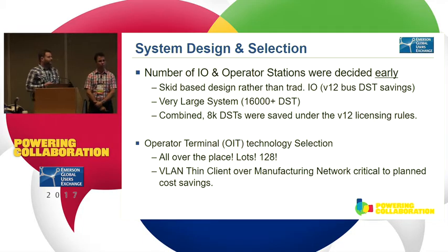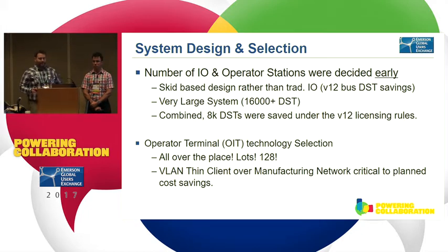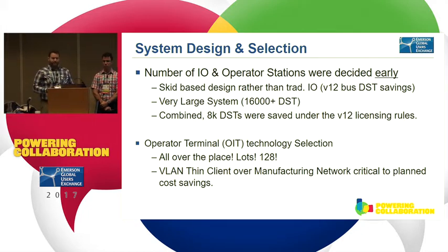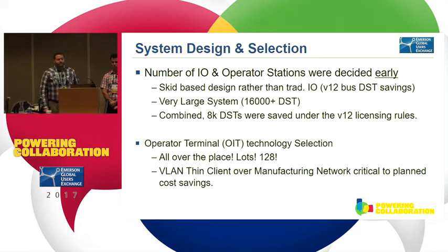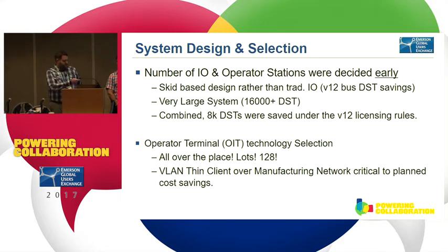So related to this, we have 128 operator stations. That's a lot of operator stations. So we had a lot of things to consider with that regarding licensing, also with network runs to those. So we went with Fieldbus and DeviceNet.